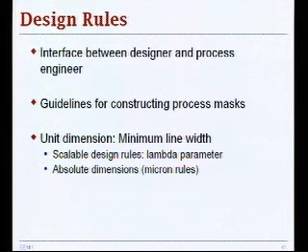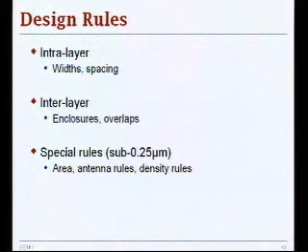So more recently, these lambda rules are still kind of in use, but most companies now use absolute micron rules. So when you have a technology, you have all your rules expressed in absolute metric units. And there are a couple of things you need to know. There is obviously your palette, your set of layers that you're going to use. So you're like an artist. You have your palette, and you can choose different colors, put polygons together, and make your artwork.